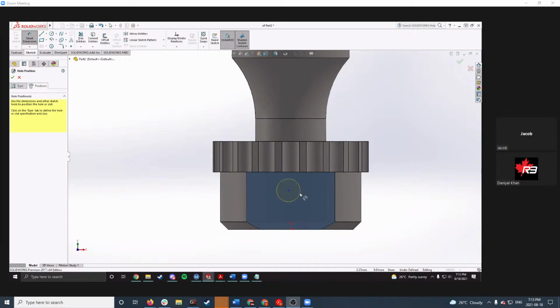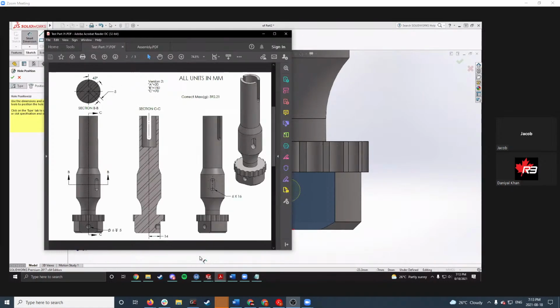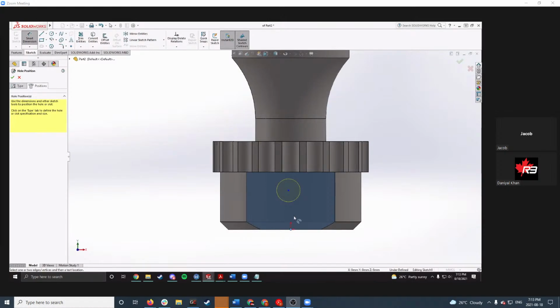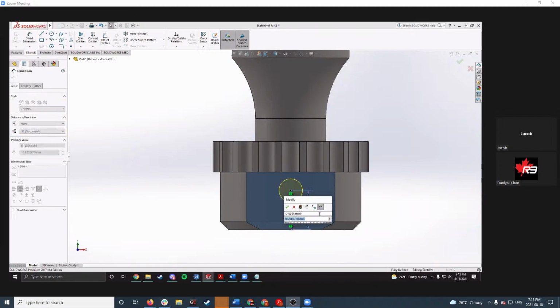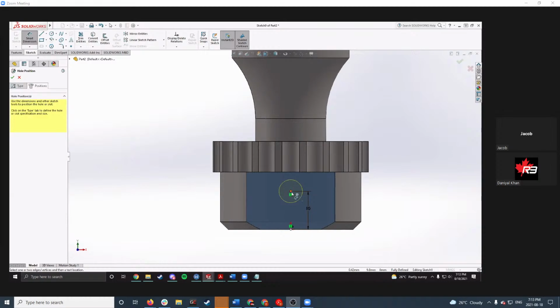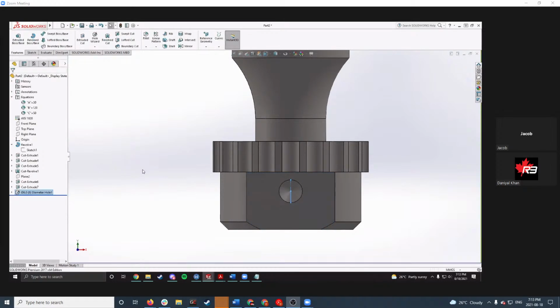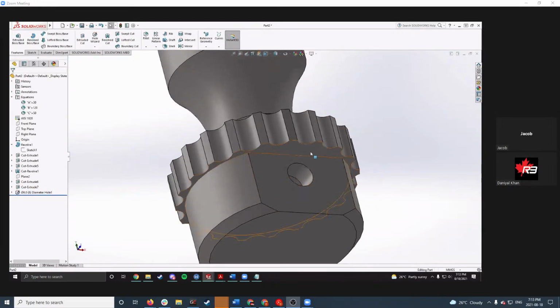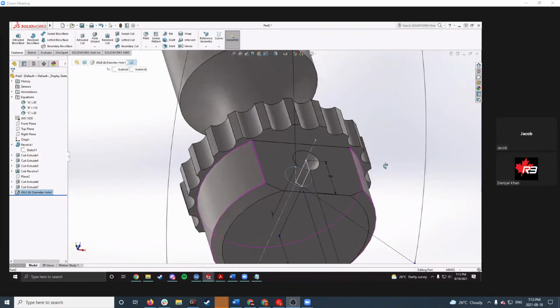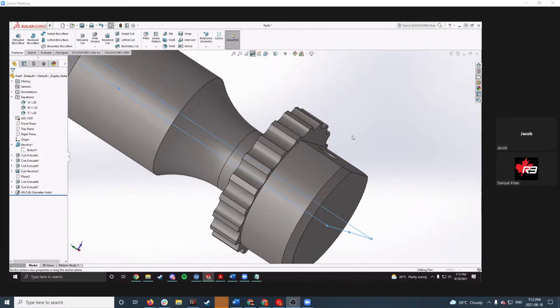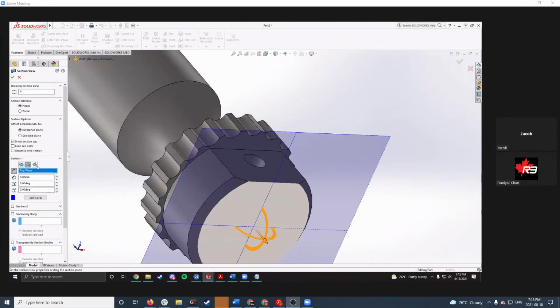And now I actually want to define where this hole is relative to the surface. So I'm just going to center this hole here, make it vertical, and then put some dimension here. Let's say it's 10. So the black dot is fully defined now. Click the check mark, and that'll make our hole here with the cone bottom. You can kind of see it here. And you can do a cross section as well to check.